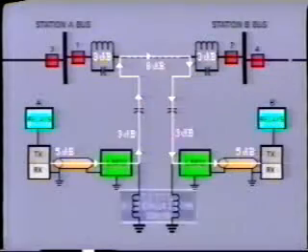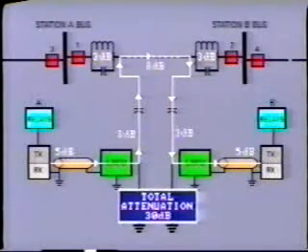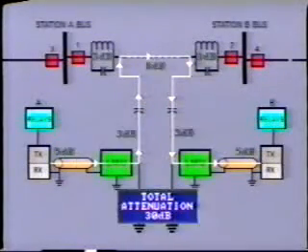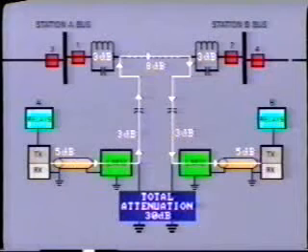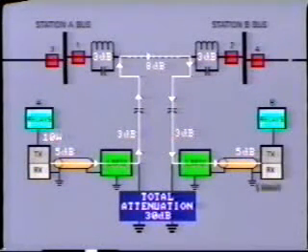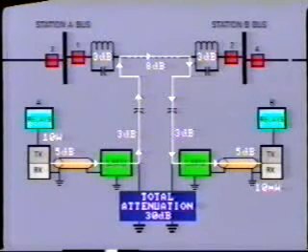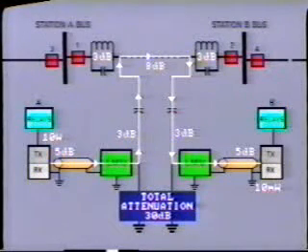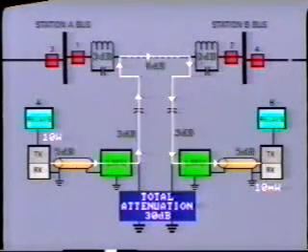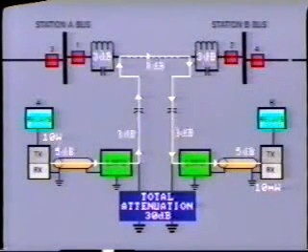So in this particular example, the total attenuation of the signal is 30 dB. What is this in terms of power? Well, if we started out with a signal of 10 watts, the power at the receiving end would be 10 milliwatts. Remember, the dB loss quoted for any particular item is a ratio of power in and power out of that equipment. So you could work out the actual power lost at each point.